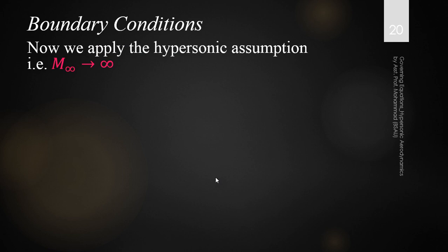Now these non-dimensionalized formats are again looking very complicated. So what we are doing now is applying the approximation. We know that we are dealing with approximate methods, so somewhere approximation is coming. The approximation is that M infinity tends to infinity. It's a very high value because we are dealing with supersonic, hypersonic Mach numbers.